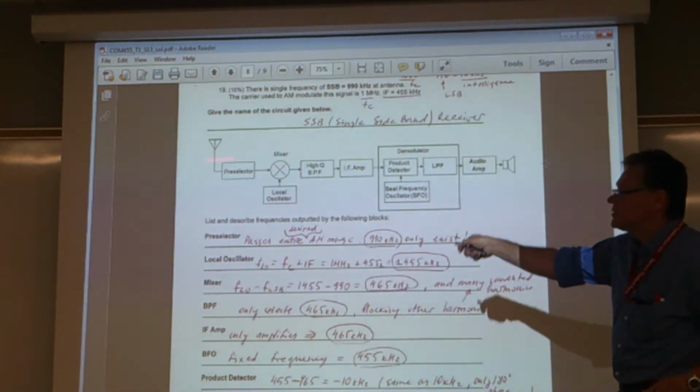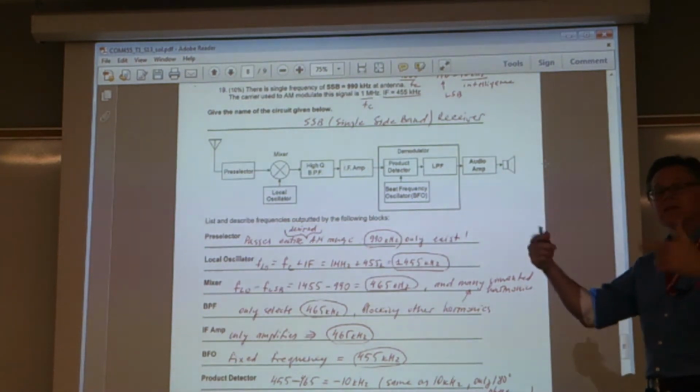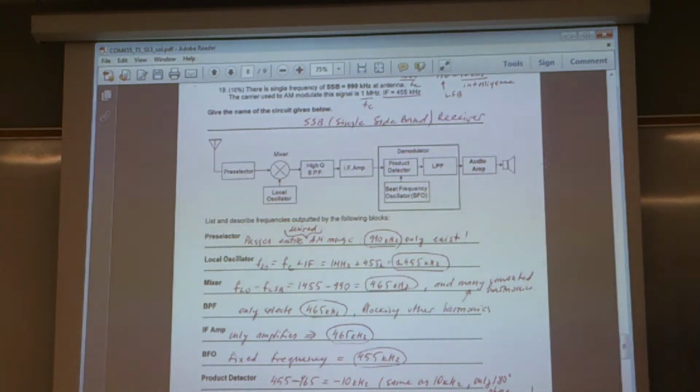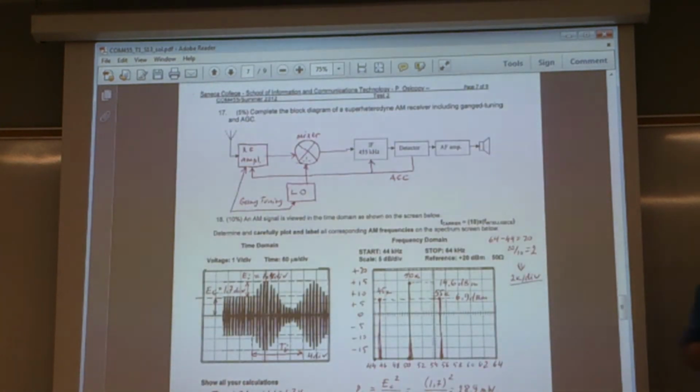You can use it and go back and reconstruct things. But what was missing here is that it says I am receiving intermediate frequency. That means there has to be a mixer producing that frequency. What does the mixer collect? The mixer collects the LO and the preselected channel.